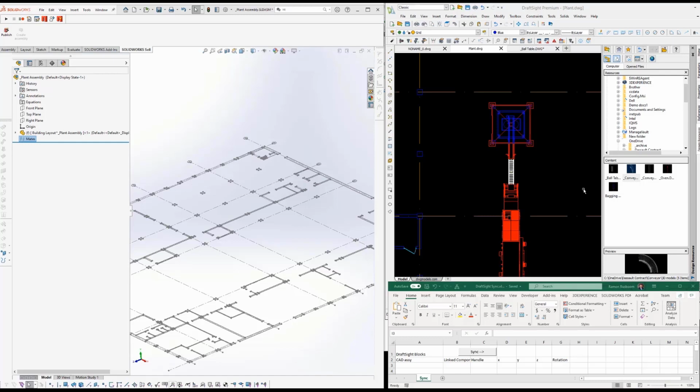So how this works is you're going to take blocks, and blocks have an X, Y, Z value and a rotation. Then I'm going to tie that to SOLIDWORKS subassemblies, and a SOLIDWORKS subassembly has something called a transform, the three-dimensional rotation and location information. I'm going to connect those two together, so if I move one, I can move the other, or vice versa. It's a little bit of math behind it, but you're just connecting those two objects. In this particular example, I'm doing it by name. These blocks have attributes in them, so I know which subassemblies I'm pulling from.